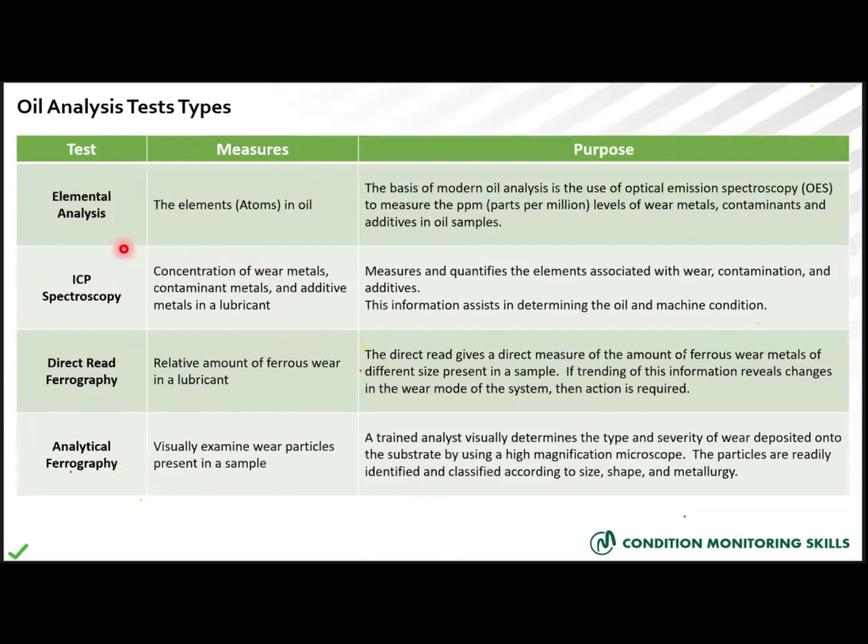We can do elemental analysis as well. We can do ICP spectroscopy. We can do direct read ferrography, analytical ferrography, and so on. So those are the most commonly used oil analysis tests. It is just an overview of those tests. Of course, anyone who is going to deeply study or take courses in machinery lubrication analysis, those topics are going to be discussed in detail.